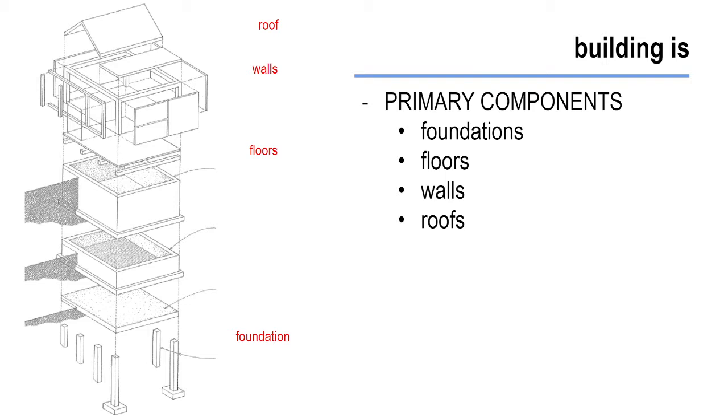Even a flat roof tends to have a slight slope towards a drain, just to keep it from becoming a pool that will eventually collapse in. An overhang on the roof is also needed to help shed water away from the building instead of just dripping down the sides.